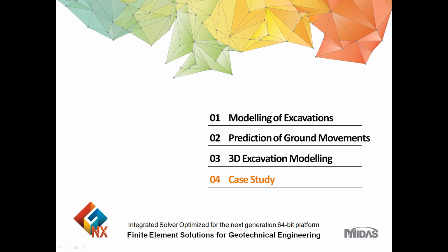The case study provides a summary of a research project related to the analysis of contiguous pile retaining walls using the limit equilibrium method as well as the finite element method using Midas GTSNX. The selected geometry, construction sequence, and soil conditions are based on a 4-meter deep excavation required for the construction of a rainwater attenuation tank at the Birmingham New Street Station redevelopment project in the UK.